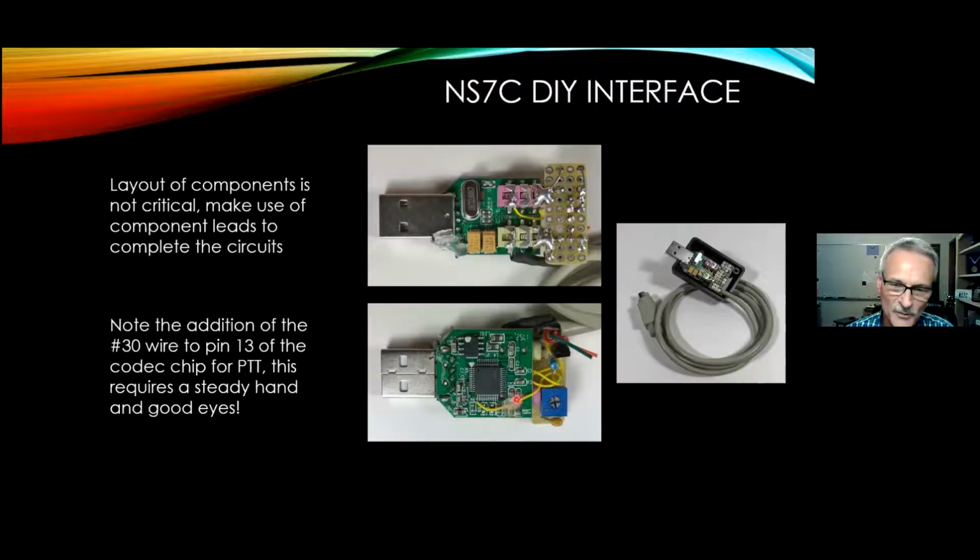I would suggest you put a little bit of hot glue on here, because if you pull on this, you might rip the land pattern off over there, and that would be ugly. And then, of course, just wire up the connector of your choice on here. In this case, I'm using the infamous 6-pin DIN, notching the case here, bringing that in, connecting it up to the various points on the board there. And that's all there is to it.